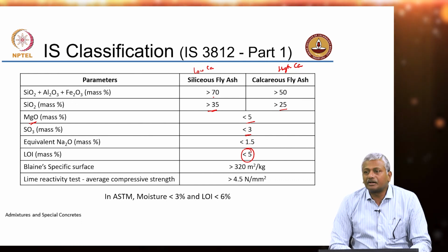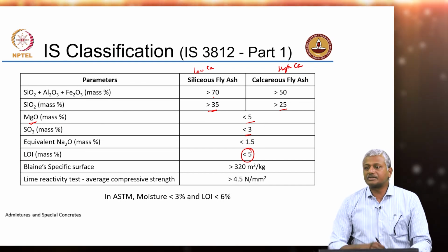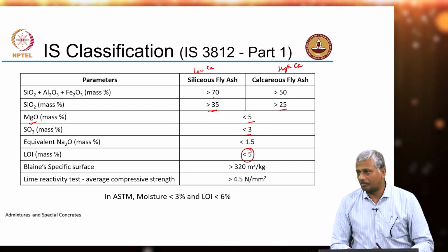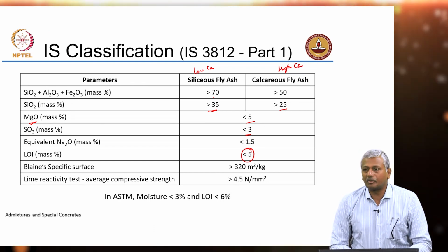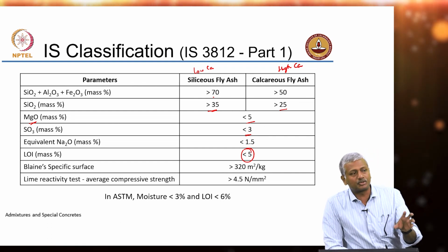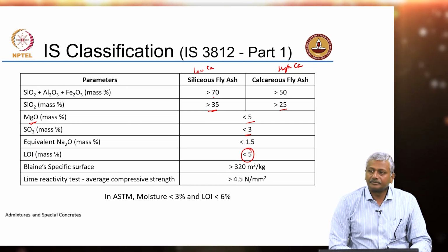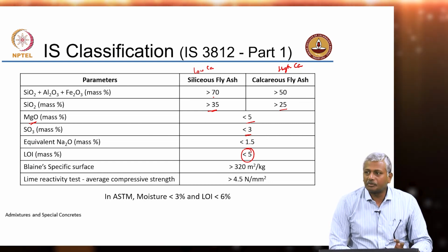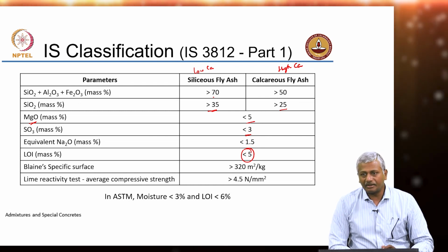you have to burn it at a controlled temperature so that the silico-aluminate that is amorphous in the case of fly ash does not start assuming some crystalline form. Okay. So, you have to be careful about selecting fly ash carefully. The boiler characteristics have to be adjusted suitably so that not too much of the carbon is unburnt, right. So, we have to be extremely careful, that is why this LOI has been specified very carefully at 5%.